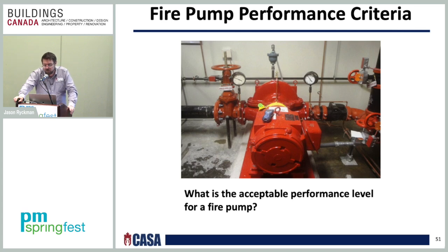Electric motors must also have a voltage reading either within 5% below or 10% above the rated voltage on the nameplate of the motor. So if you have those issues, there's something going on and you have to fix your fire pump.